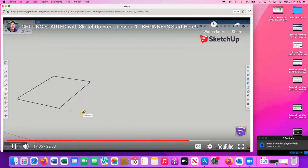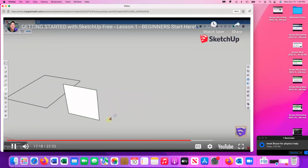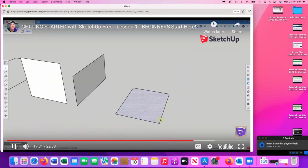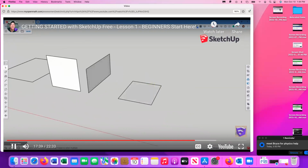So let's do another example. If we activate the rectangle tool by tapping the R key, you can see how I can tap my left, right, or up arrow keys in order to dictate if I'm going to draw a rectangle along the green, along the red, or along the blue. So by tapping those arrow keys with those tools active, you can force this to draw along whatever axis you want. And so in the remaining time, I want to talk about going to 3D inside of SketchUp.